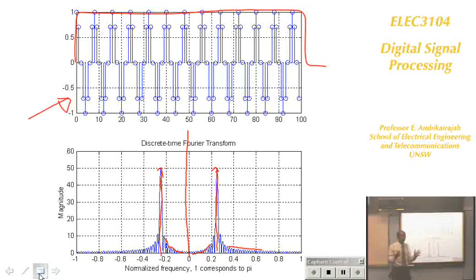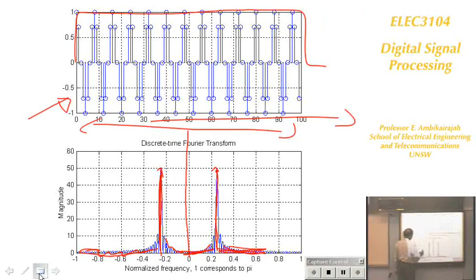As soon as you group a signal, this rectangular window effect comes in. That causes all these problems. If your window is very, very large, that means if you take this signal of infinite length, then you will end up with all these sharp peaks like this, with virtually zeros elsewhere. This is the windowing effect, that making the window small causes this problem of a ripple.